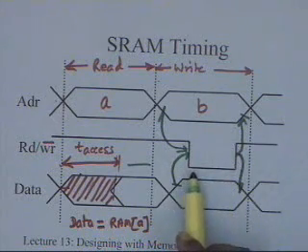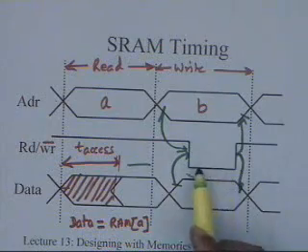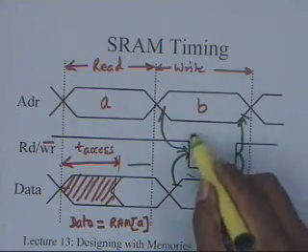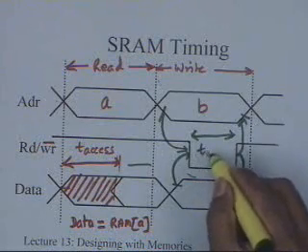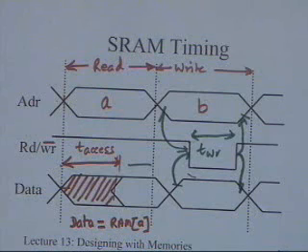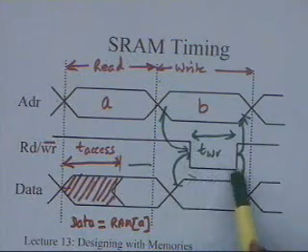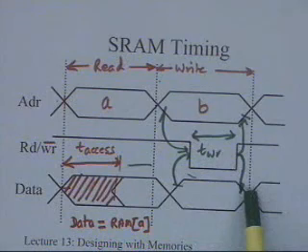And typically most RAM devices are not edge trigger devices. The flip-flops that are there are level trigger devices, and you essentially specify a minimum period for this. This is the T write pulse, the minimum width that is required. So during this time, this is like the setup time and this is like the hold time as far as the data edges are concerned.